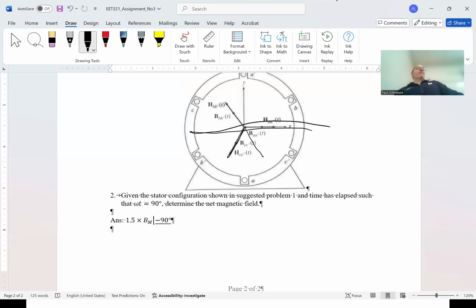Well, keep in mind, I have a resistor and an inductor. Those aren't line-to-line resistors and inductors. You only have a single phase resistor and a single phase inductor. So we have to represent those as single phase quantities. We can't throw in line quantities in there and get the correct results. We have to do everything on phase relationships.